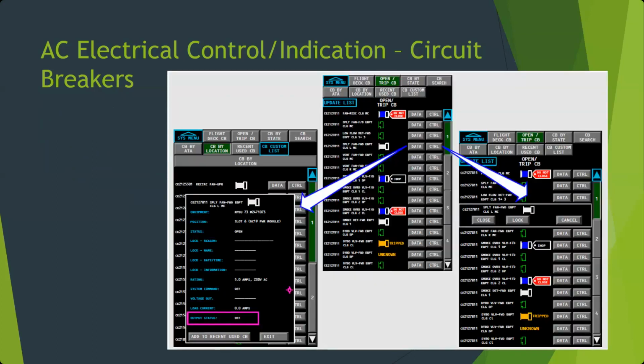But your newest aircraft, here's an example of an ICAS system that has the circuit breaker control on it, with the actual circuit breakers being remote control circuit breakers that would be down in an electrical bay somewhere. And so you have different breakers. You can see, like here in the middle one, we've got fan, miscellaneous, and they put a little do not close. The maintenance can go in and actually lock them in an open position with a virtual collar.